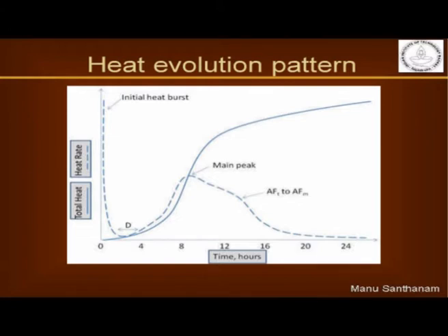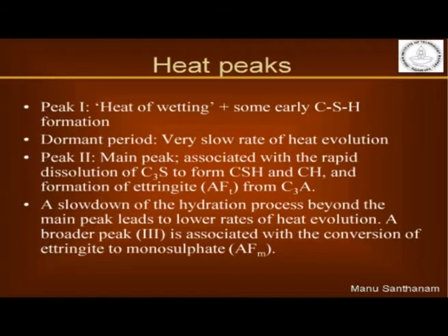So now let us try and understand the meaning of these peaks and what reactions they can be attributed to. The first peak, the initial heat burst, is only because of very early surface reactions that happen on the surface of the cement particles, and we also call that heat of wetting. After this we see a period where the rate of heat evolution is very small, and that period,